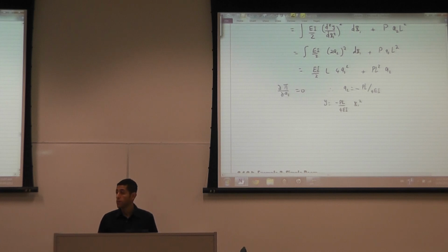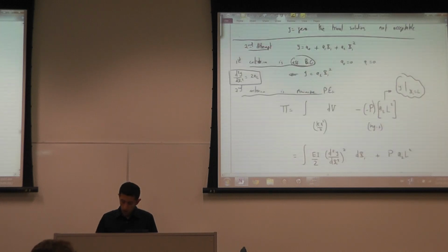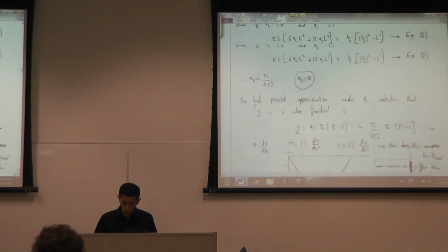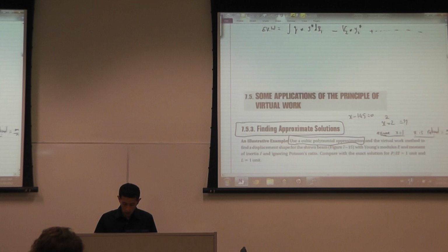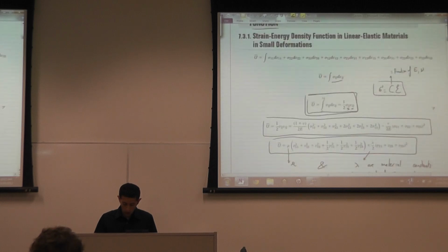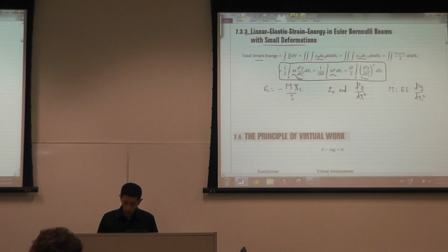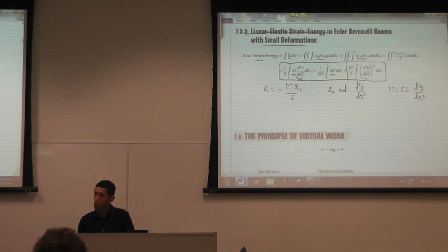Yes? How to get the equation for the energy of the beam under moment? I'm going to just scroll up all the way to here and utilize this one. It's the linear elastic strain energy in Euler-Bernoulli beams with small deformations.